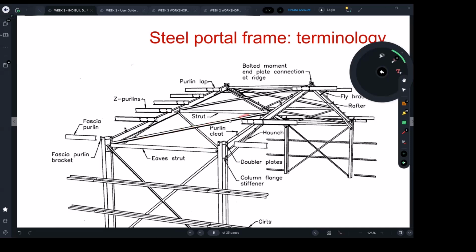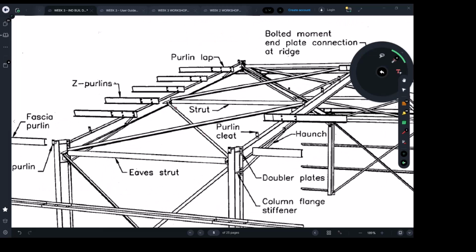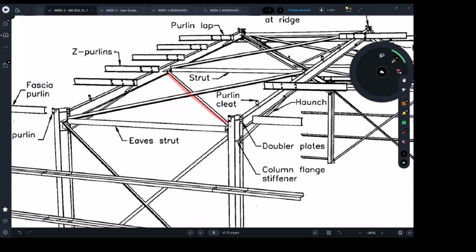This is a roof bracing here. These elements, which I can't see, they actually did not mention them. These X, I'm not sure if they mentioned them anywhere. No, I can't see that. So this member here and that member is the roof bracing. This member here, between the roof bracing, is a strut. It takes the compression from one side to another.